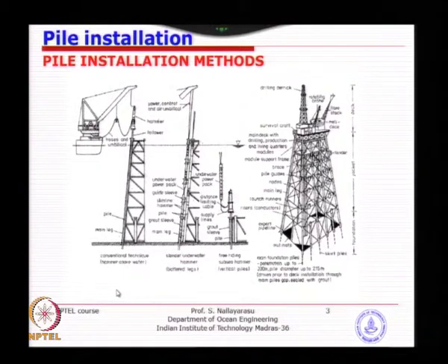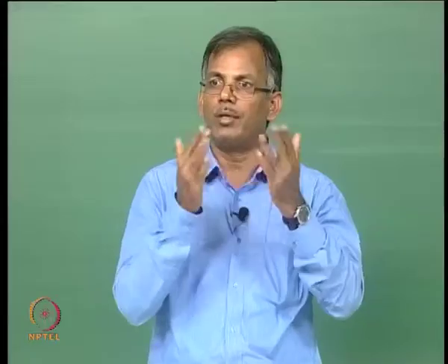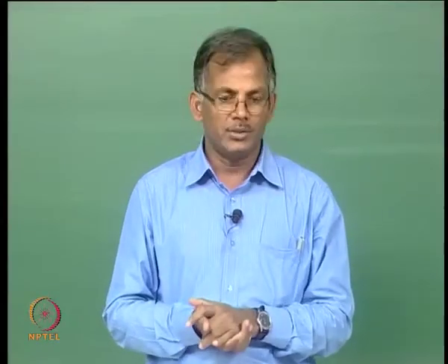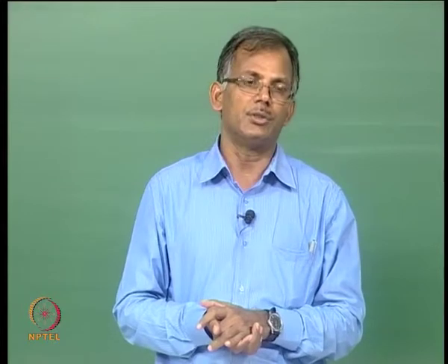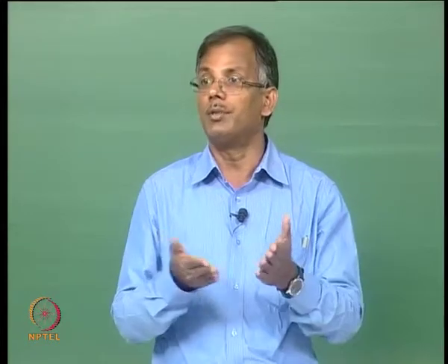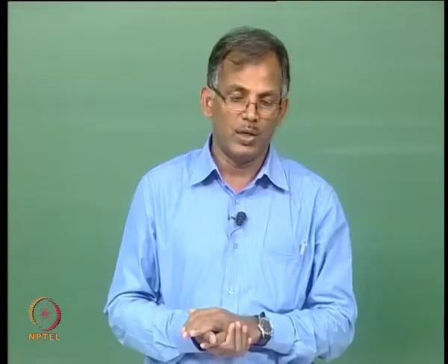So main pile installation is slightly tedious, but one thing you should notice, all the time the machines are above water. So what you have seen just now, nothing is done underwater, everything is above water, visible. So you do not need to really go down into underwater conditions. That is a great advantage, because diving is not involved.